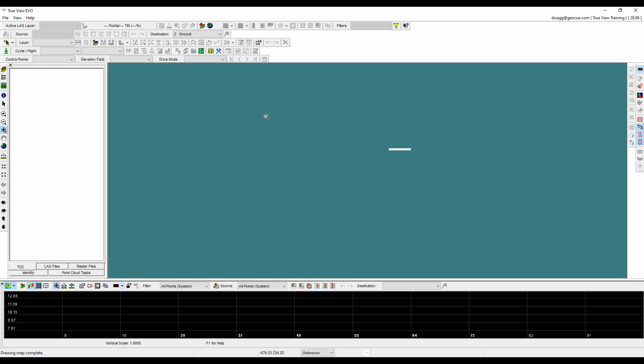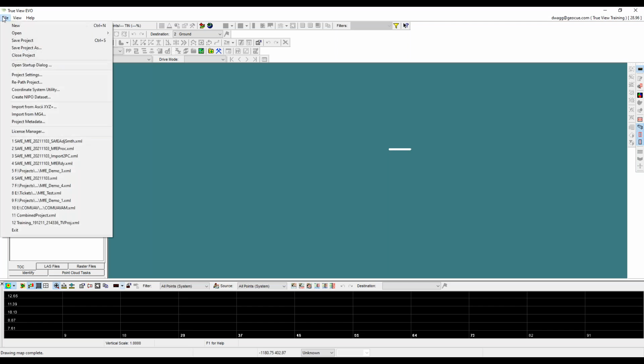Metashape is a little bit more involved, but not too much. There are what we call the Metashape for EVO licenses, and we've been handing out licenses for this since probably about June, I think, is when the first of them started rolling out. They're a console license of Metashape, so you can't run the GUI version of the software with it. So what we did is install this headless, non-GUI version of Metashape with the installation of EVO. And in order to license it, you'll get a license key.